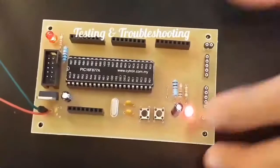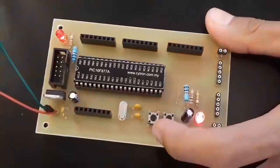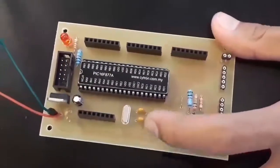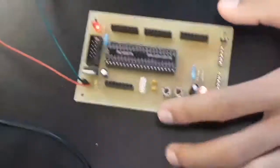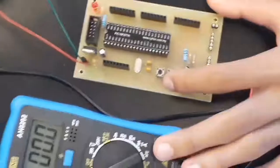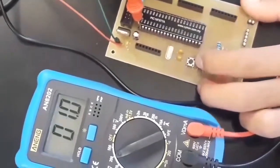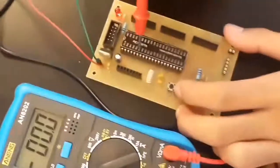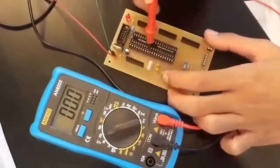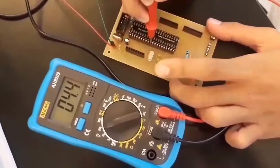This is the result when the board is connected to the function generator. LED 1 is lit up and LED 2 is blinking. When button 2 is not pushed, the reading on the IC leg 1 is 5 volts. But when the button is pushed, the reading becomes 0 volts. When button 1 is not pushed, the reading at IC leg 10 is 5 volts. When the button is pushed, the reading becomes 0 volts.